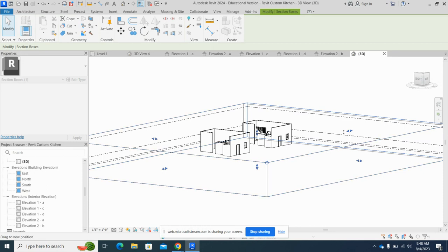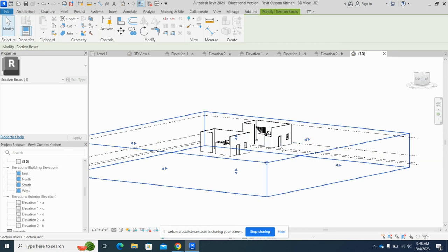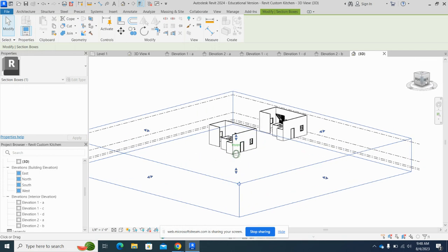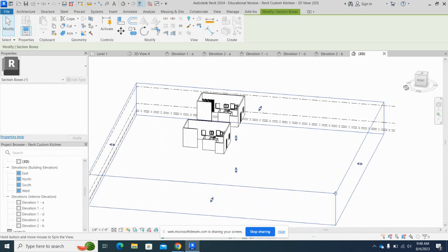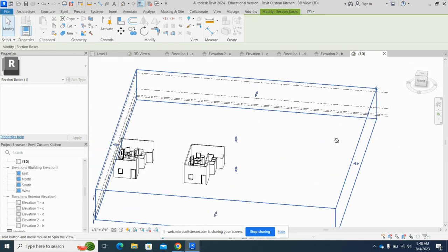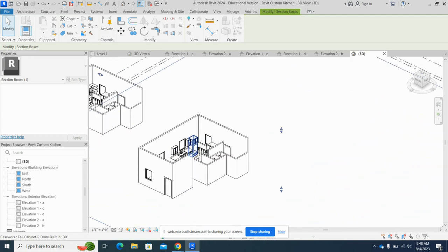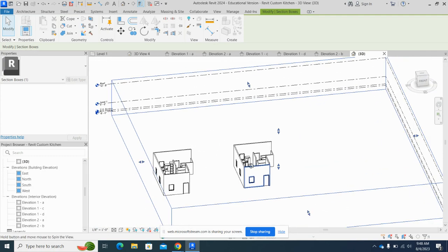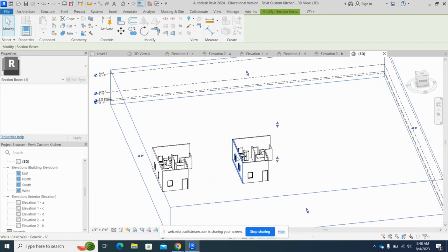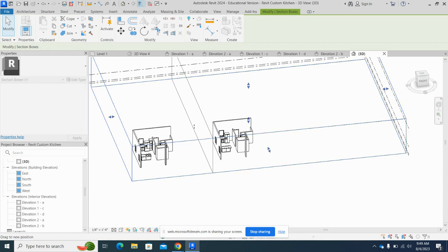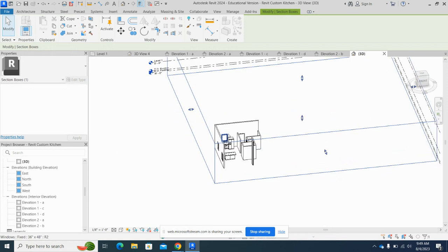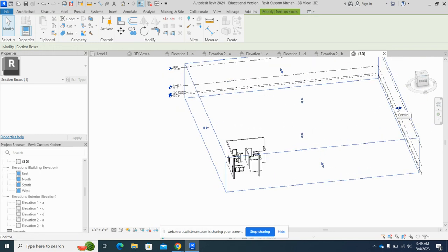A couple things with this. You can use the drag tools to adjust it. Then you can click and drag to turn and rotate it for pivot, or if you hold the shift key and push in on your wheel and turn that, it will turn it as well. Whichever is easiest for you. Go ahead and pivot so that you can see the opening where you want to draw. Then I'm going to adjust my arrows to isolate that view as it goes through.